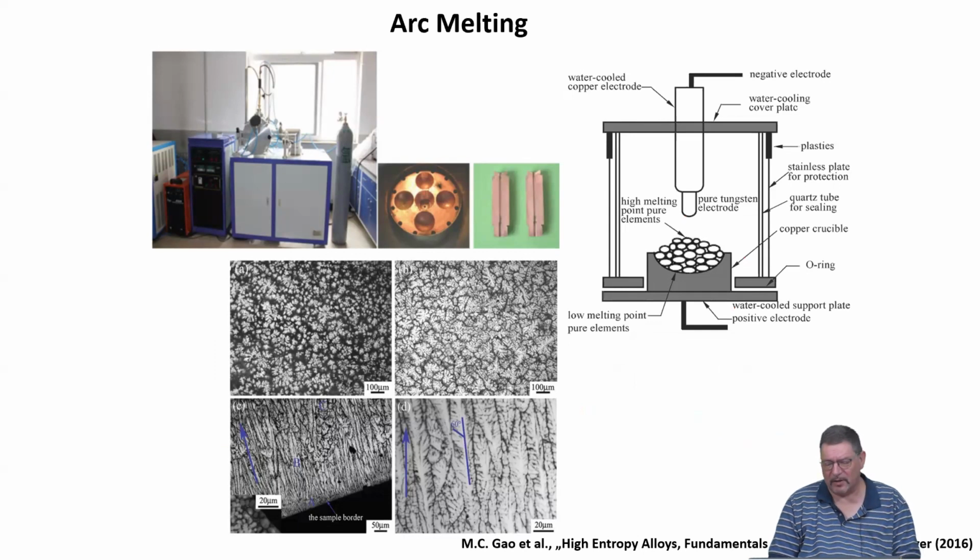You also know? Okay, then I don't need to talk much about it. It's obviously a process which works very well. You just assemble different ingredients. You use a high power electron beam to melt the material while it's situated on mostly a water-cooled copper plate. And then you go through the liquid phase, and once you stop the beam or take it away, the material freezes again. When you did this yourself, what are the problems with this method?